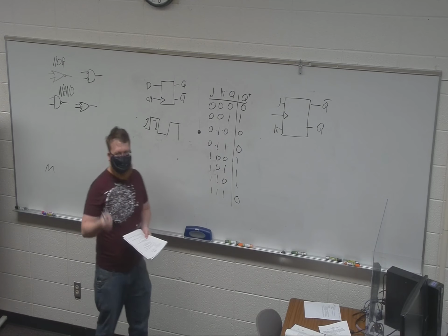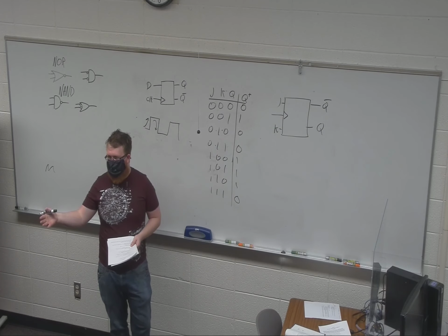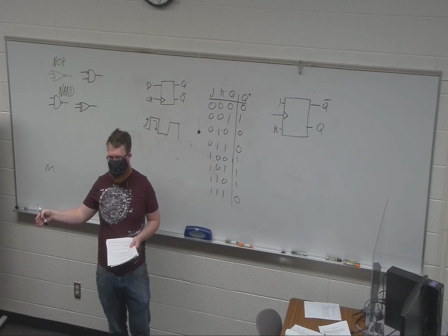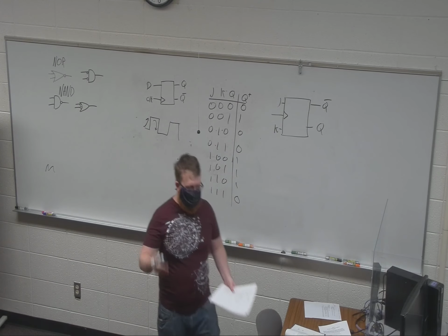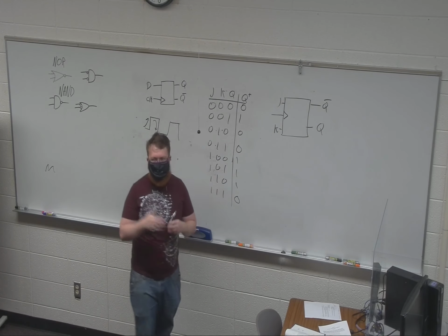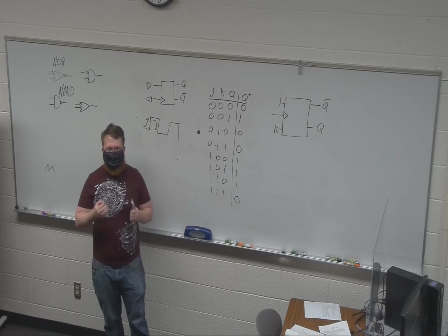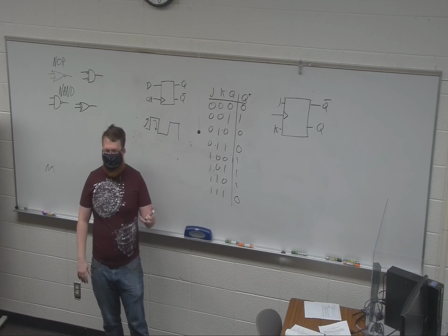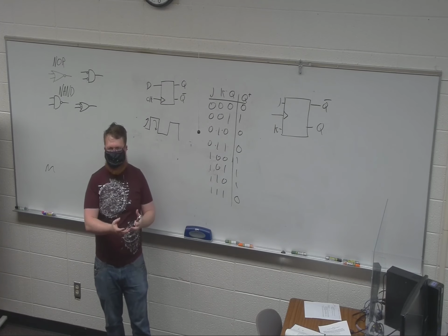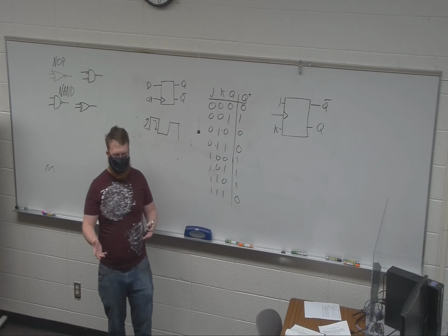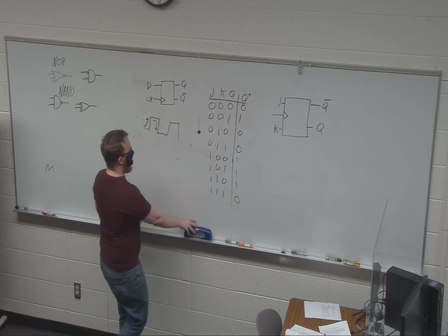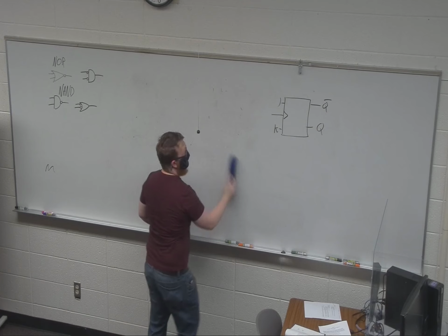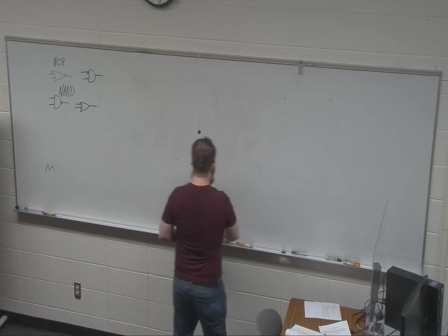The trade-off then is that the outputs have additional information on a Mealy, which in turn means that a Moore state machine has more states. So for most people, it is easier to think about Moore state machines because you're only worrying about what state you're in to determine the output. Mealy has the advantage of fewer states, so simpler to design if you were a robot, but we're not. So we're going to go through an example of each of them, and we'll look at the system.